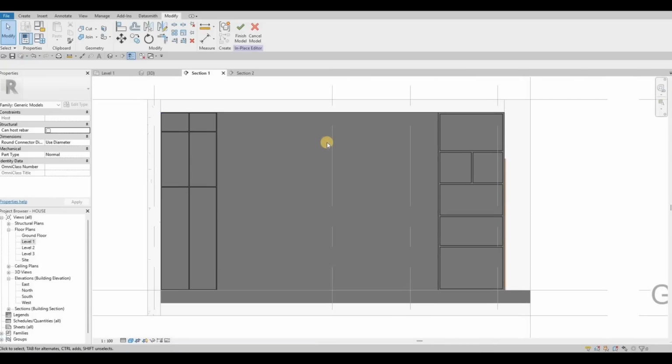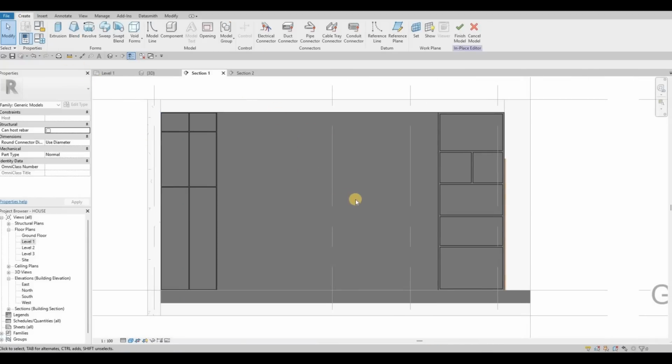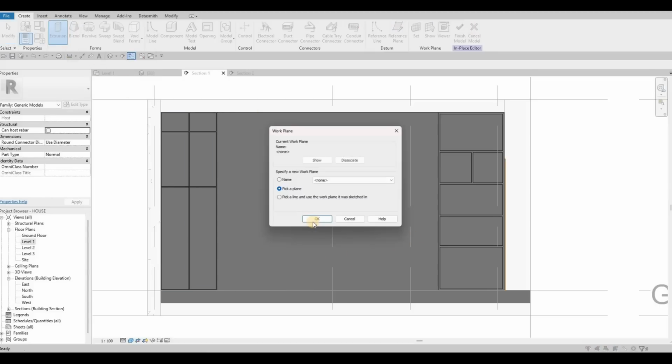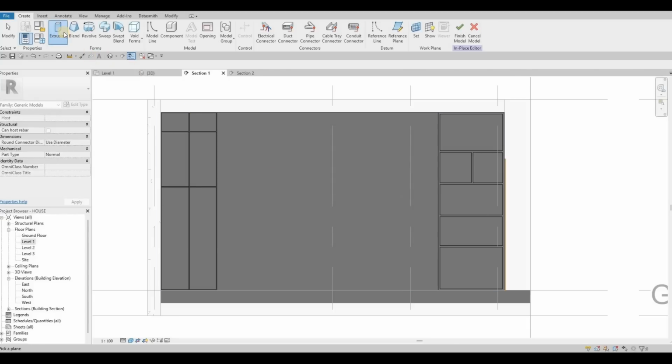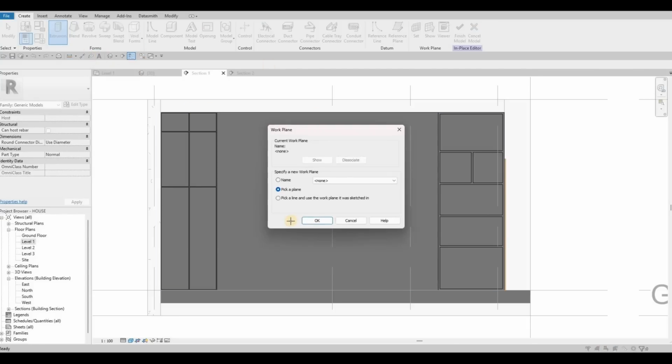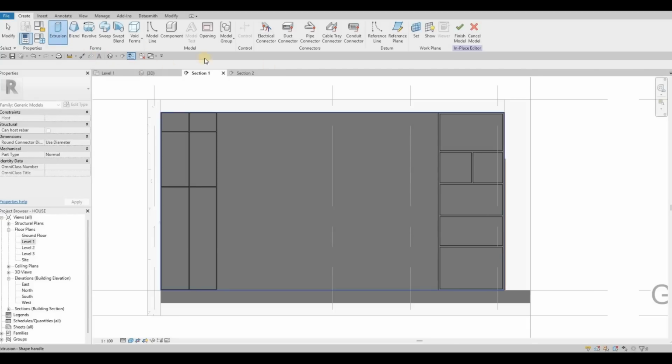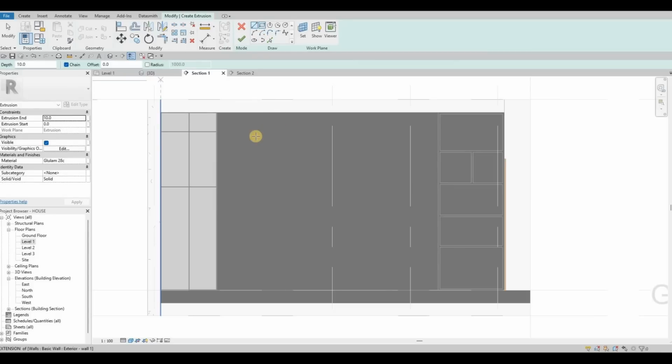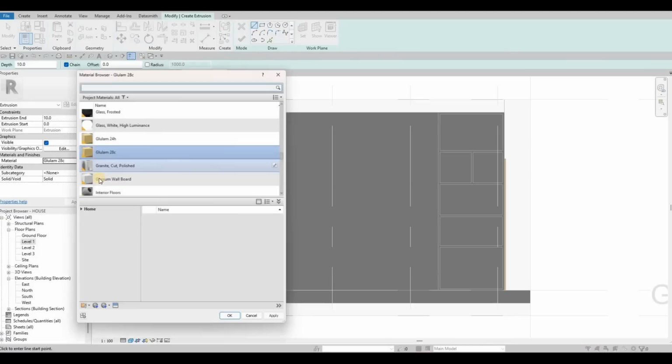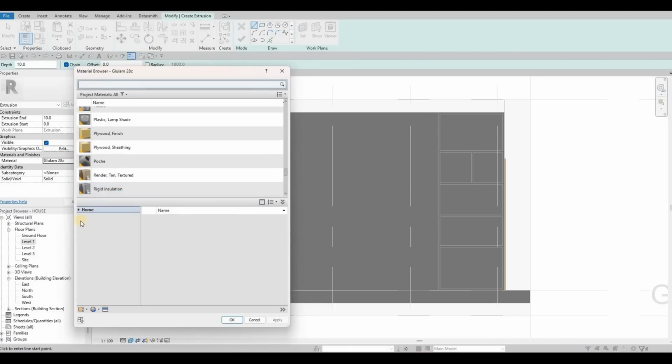and then now we need to add some decorative pieces as well. I want a mantle, a small mantle right here. So I'm gonna do an extrusion, and then pick a plane. Make sure this is the wall, not the wall, but the back of this. And then we need to change the material to one of the stone materials right here.